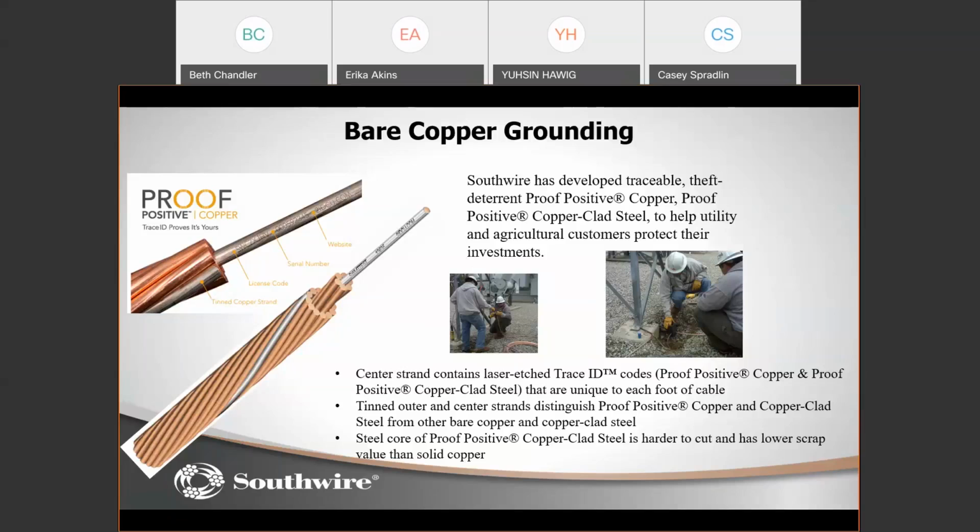So high density polyethylene, because of the higher molecular weight, has a higher density. In terms of humidity, there is an ASTM test method called the moisture vapor transmission rate test method. HDPE will have a lower vapor transmission rate compared to its counterpart, LLDPE or LDPE.